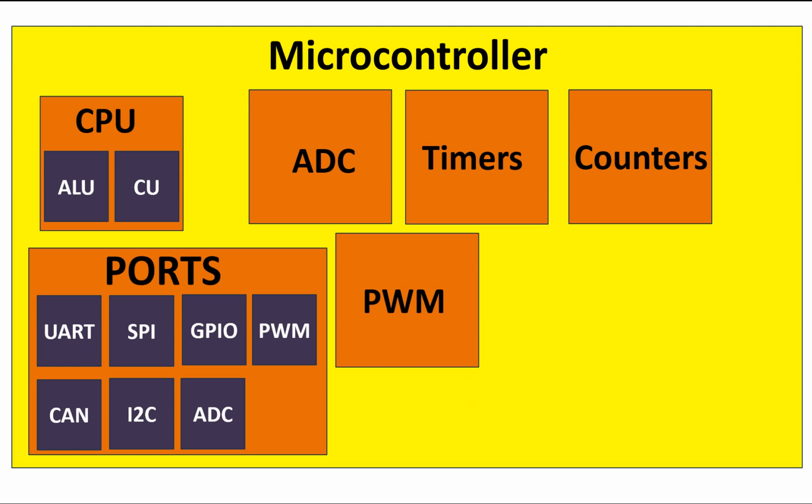And then you have a pulse width modulation module in a microcontroller. In some you have it, in some you don't, but microcontrollers do support this. This allows you to control the speed of motors etc. Like for peripheral devices like a motor, you just use a transistor and a motor, then you send PWM commands. This will allow you to control the speed of the motor, or in short it will allow you to interface the motor with a microcontroller. Just like if you want to interface a motor with a computer, you will use the same module in some form.